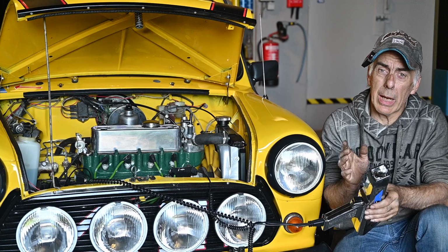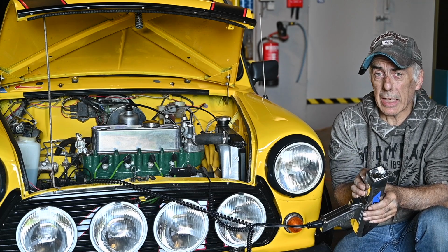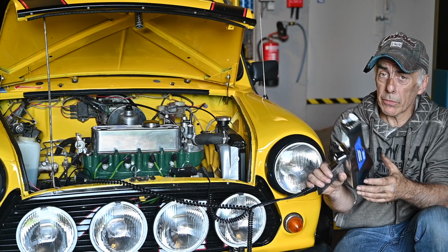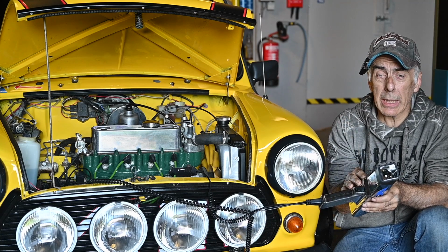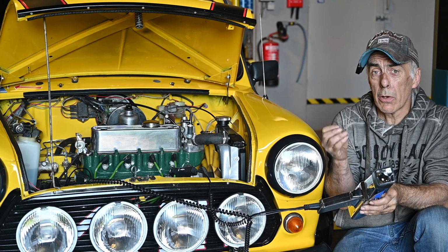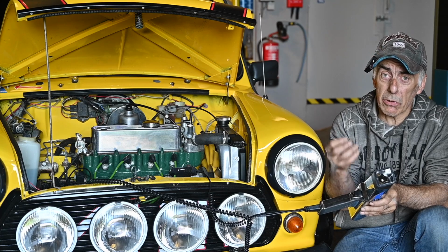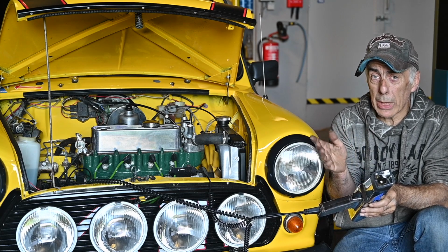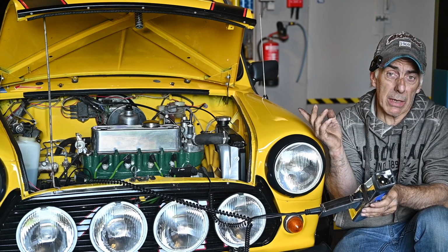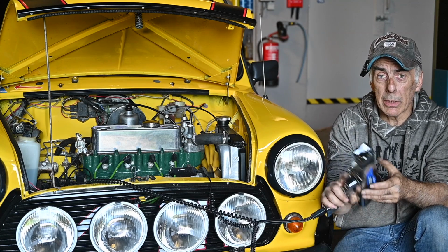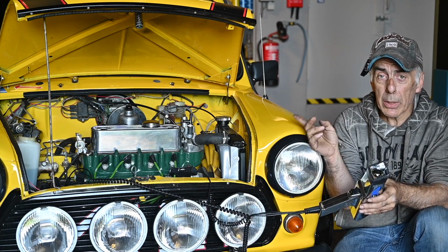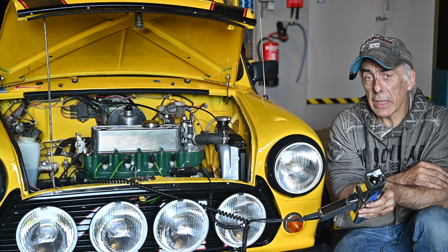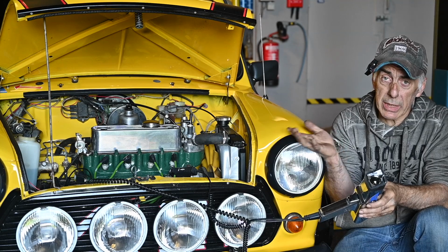So what we're going to do now is check the dynamic advance, and for that one you're going to need the strobe light for sure. There's no other way around of doing it. I hooked up the vacuum hose already, so I'm going to crank up the engine. I'm going to run it at 1,000, maybe 2,000, 3,000. I will run it in incremental steps and have someone do that, or you adjust the gas throttle yourself. It's all up to you. And then I'm going to use the strobe to light up the markings on my crankshaft pulley and on the fingers on the distribution cover in this case.